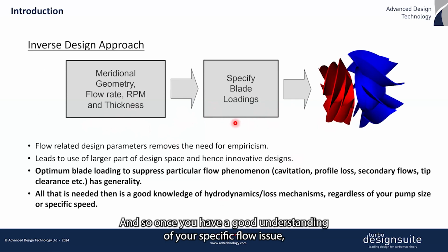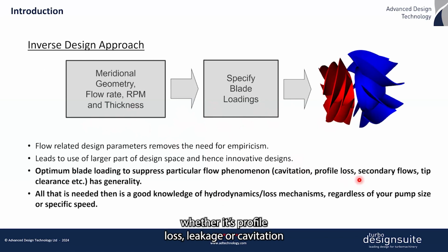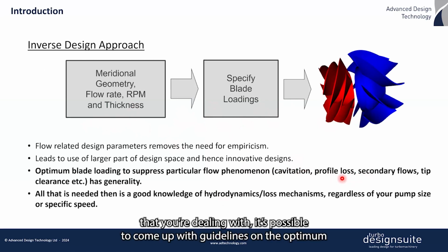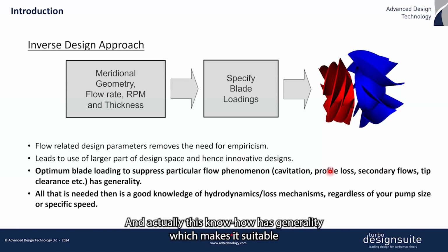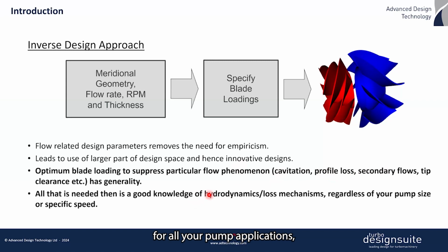And so once you have a good understanding of your specific flow issue, whether it's profile loss, leakage, or cavitation that you're dealing with, it's possible to come up with guidelines on the optimum blade loading to tackle each of these issues. And actually this know-how has generality, which makes it suitable for all your pump applications.